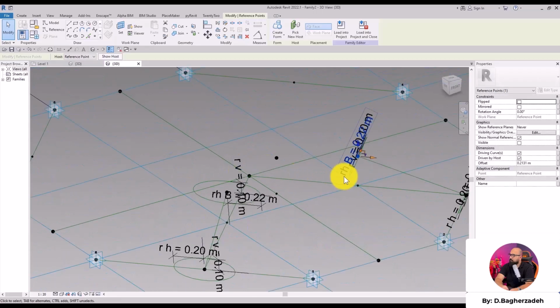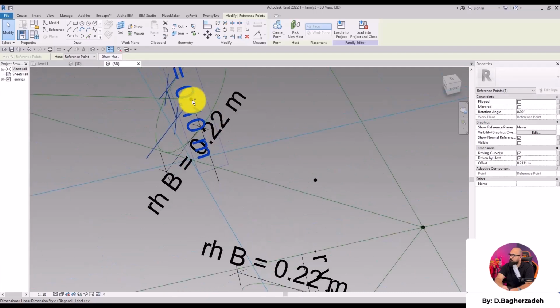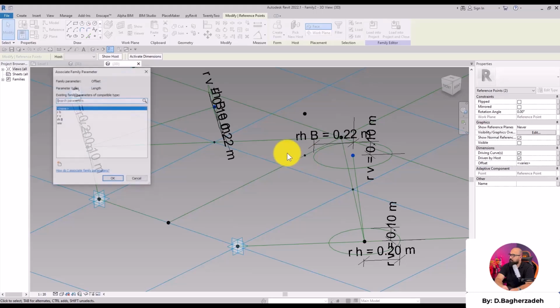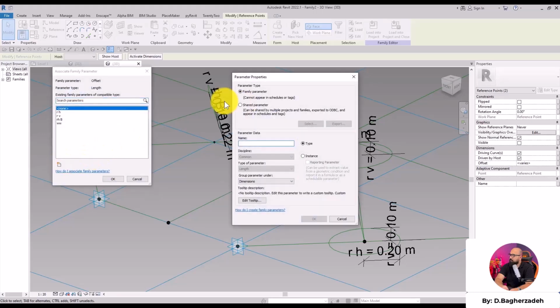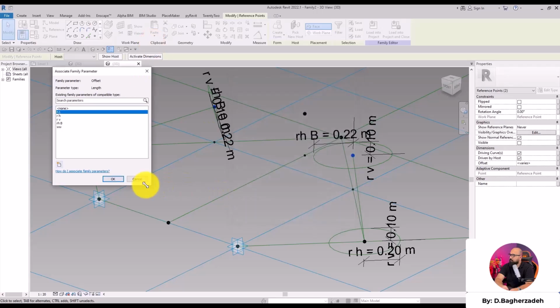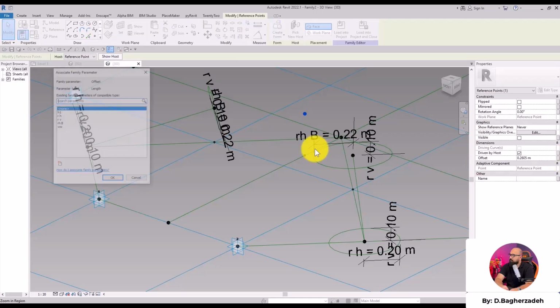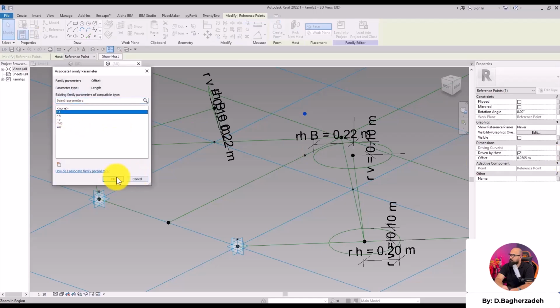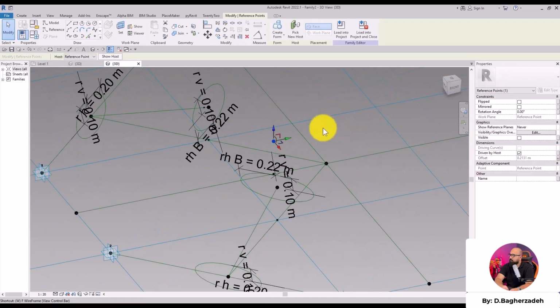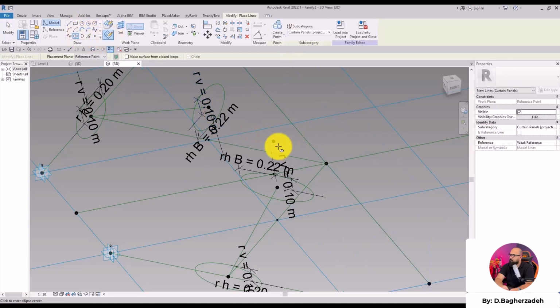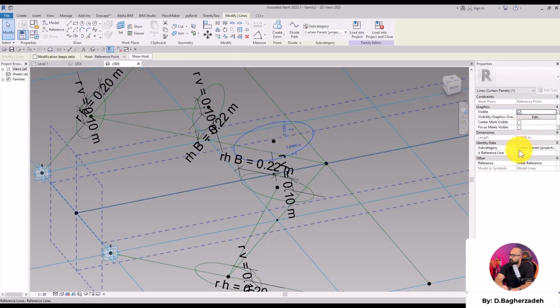So let's select these 2 points first. And again, guys, pay attention when you're doing the selection because the viewport is getting more and more crowded by the minute. All right. For the name of this parameter, I'm going to go with H1. Okay. And both points will have the same course now. Let's select this and set this H1 parameter for it as well. All right. Now, set the next work plane based on this point and then activate Draw on Work Plane and set another ellipse like this. And make it a reference.